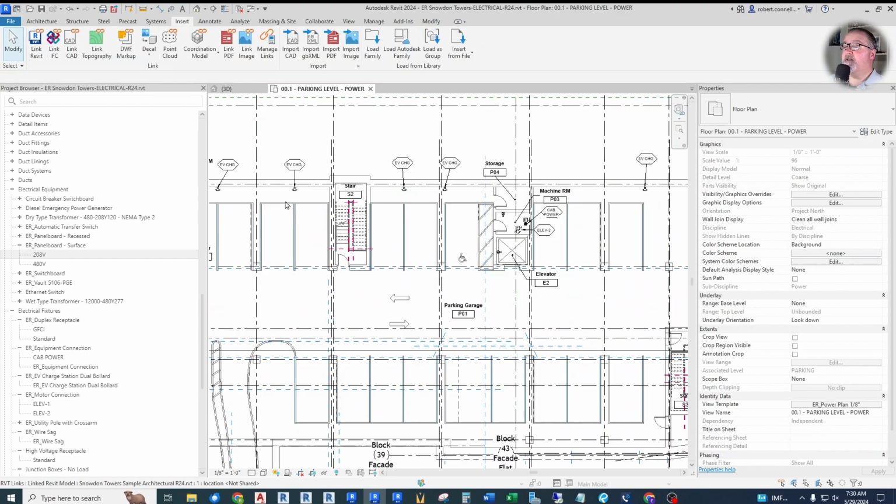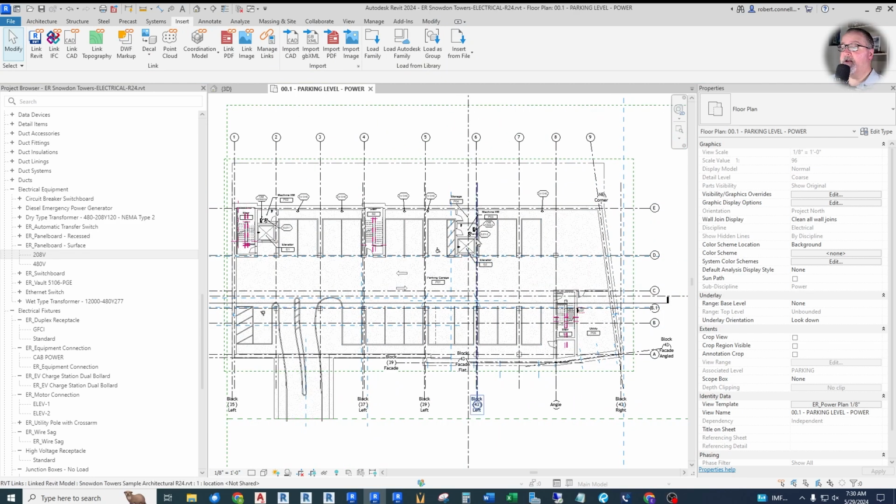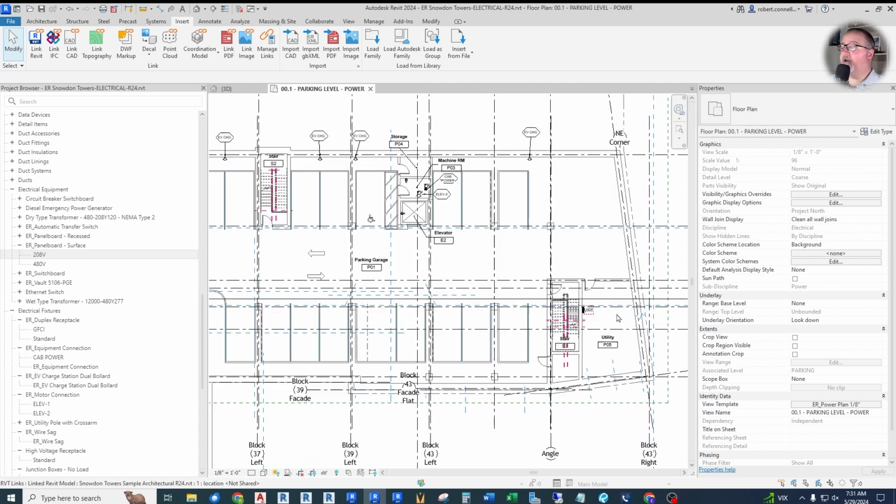And then we want to connect the elevators. Now, it depends on the jurisdiction you're in, again, as to whether you need an elevator or elevators on emergency. You need a generator. You need 2 different utility connections for backup. So in this building, we're just going to say that this building does not require an emergency system, and we can put one in later for an example if we want. For now, we're just going to connect them all to the utility power HDB.